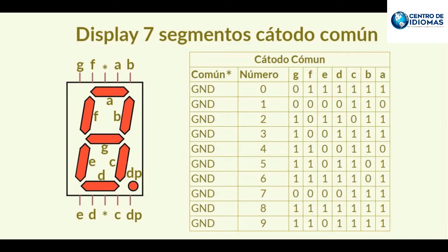It is important to mention that 7-segment displays are built with LED diodes, which require a maximum current. In other words, it is required to place a resistance to limit the current. This resistance depends on the current that you want to supply to the LED as well as the voltage drop.